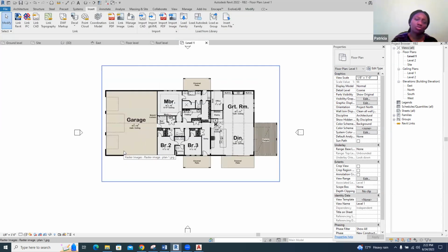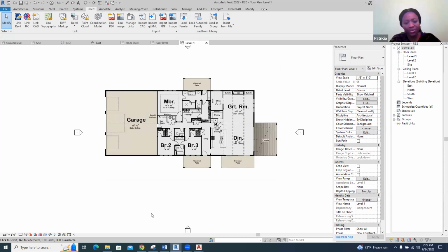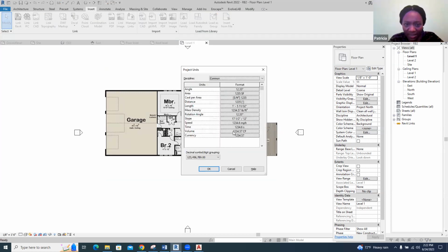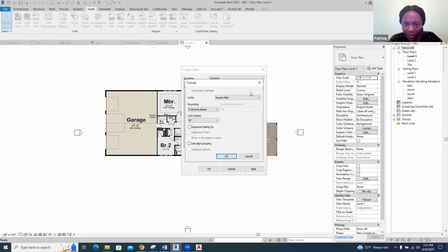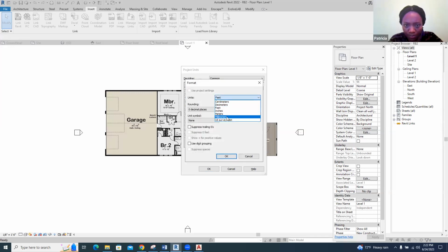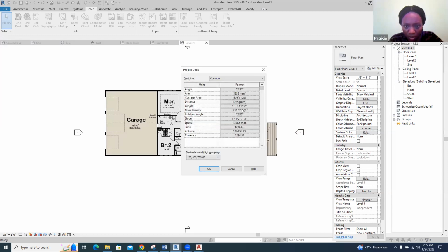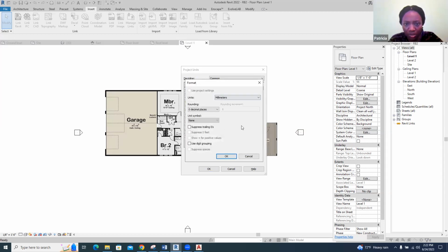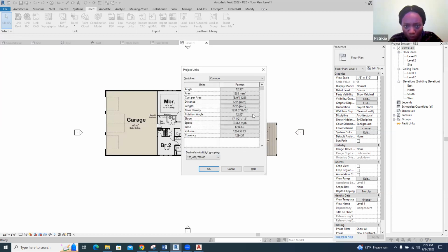The first thing we want to do is to scale it. So what units are we using? If you type UN, you can select and see, or go through it and see what kind of units are in place here. So I'm seeing meter, what you call square feet, and cubic feet. So for here, let's change it to what we used to, the millimeters. Okay. And then go to distance. We want it in millimeters. And then we go to length, change it to millimeters. So most of all this, we'll be using the length, the distance, the area for this one. So, okay.